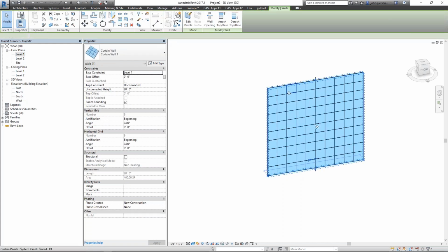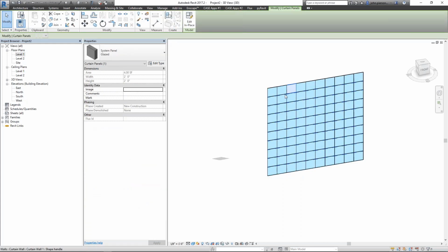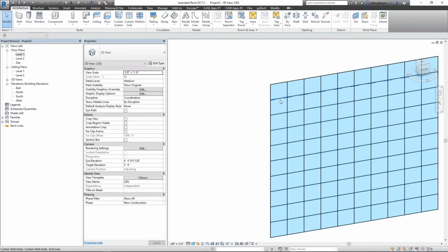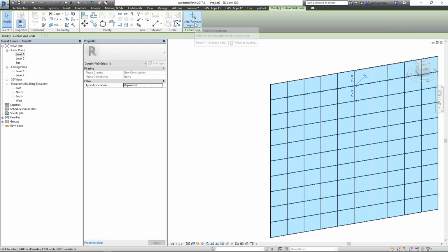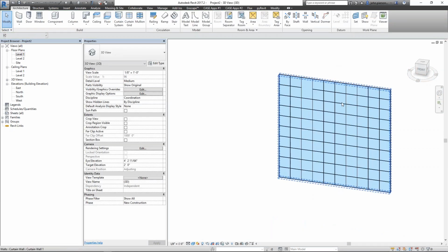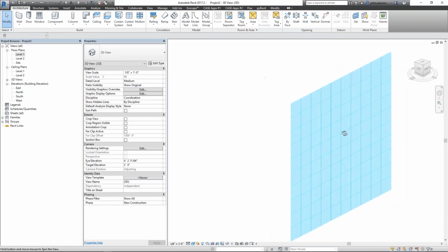In Revit, we're given this really cool little magical tool. If I tab select a grid line, if it won't tab select all of them, there it is. If we tab select the grid line, we're given this cool option of removing segments. So if I go through, I can start to remove segments and get different panel sizes that are schedulable. The area is pullable. You could shoot elevations, 3D views, all that stuff. But I don't want to go through and do that to every grid. That's not the funnest thing in the world.